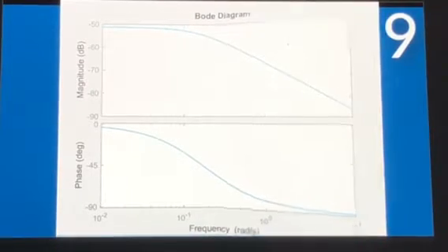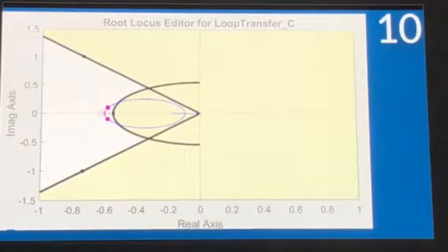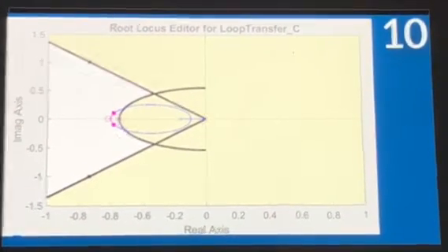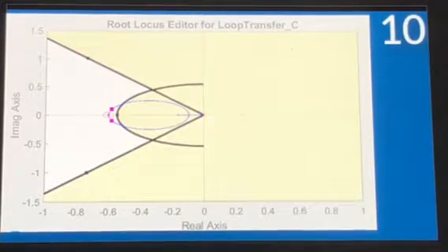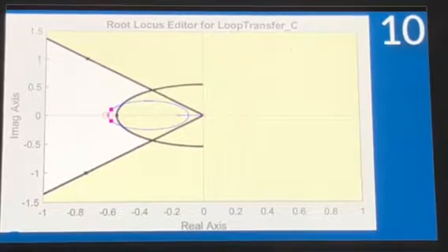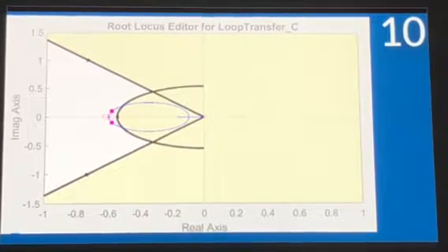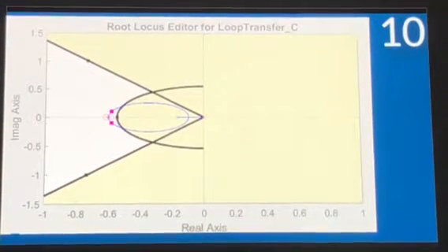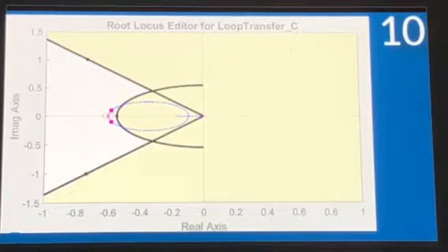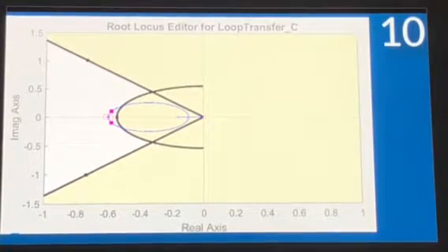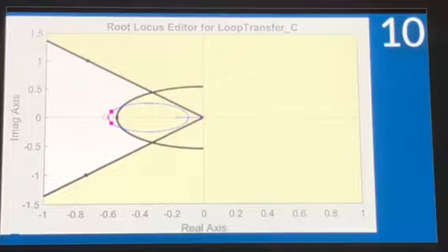With that in mind, on slide 10, we took this system and constructed a root locus in MATLAB with adjustable parameters, and we had to make sure we could get everything into the white. We were able to do that, and at this point, we had to consider the different PID control systems. We decided that it was appropriate that the system have a 10% overshoot with a natural frequency of about 0.55 seconds. This translates to 4 seconds of rise time to get to our target speed on the highway.